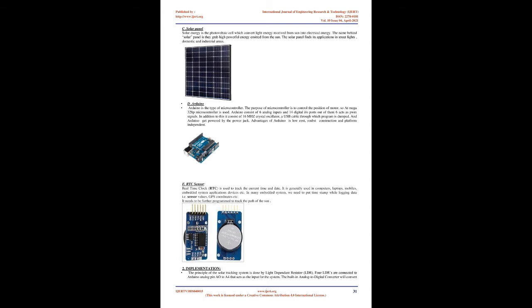10. The paper 10 shows that it is almost unanimous that single-axis tracking is better than stationary panels. And dual-axis tracking is better than both either the stationary or single-axis tracking. Though there is no unanimity of the improvement, where it was reported that the increase in energy extraction varies between 12 and 69%, though it looks 69% is exaggerated. But the issue in tracking using either single or dual axis does not necessarily mean accurate tracking nor more harvested energy. Almost all the reported techniques are based on LDRs.